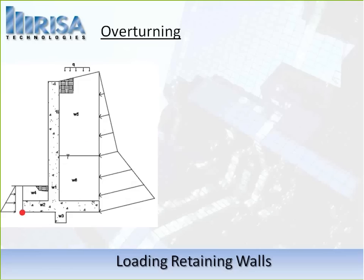And then we're going to start talking about some of the design checks we do on this retaining wall. So overturning is one of the big things that we do in this wall design, and we check this overturning based on the extreme edge fiber of that toe right there. So right where that red dot is, that's where we're checking our overturning. And each section is taken into account.